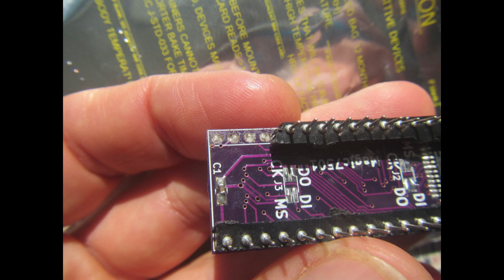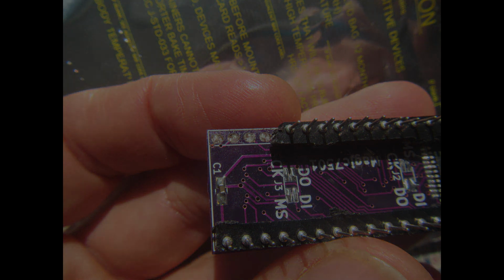These not only made the first prototype a bit too tall, but turned out to be too unreliable because the SMD pads are not really strong enough to withstand many insertion cycles of the adapter. Here you can see that some of them were ripped off when I removed this adapter from a socket a few dozen times during the various tests.